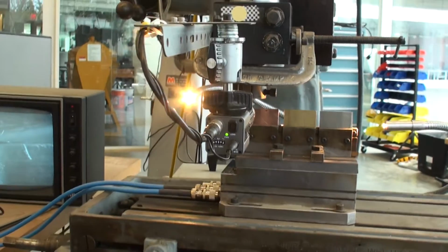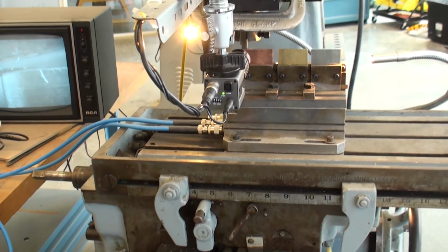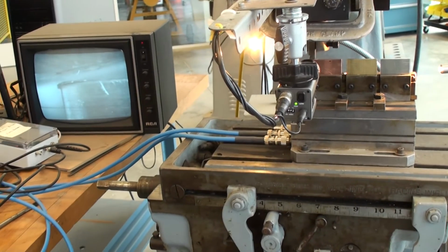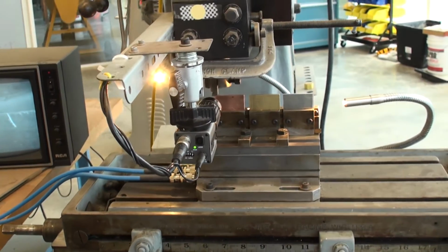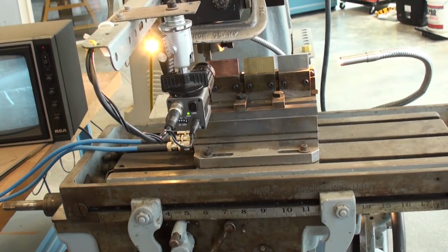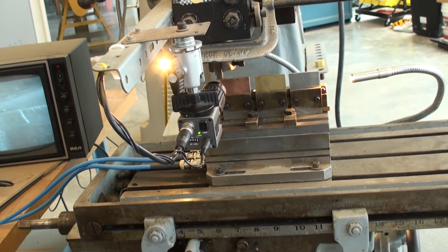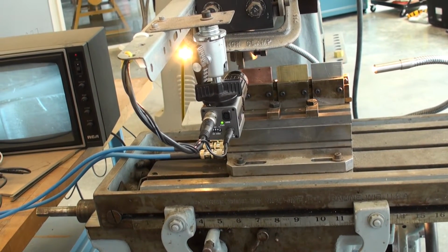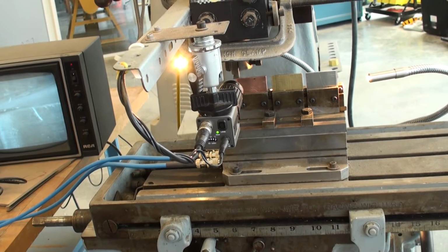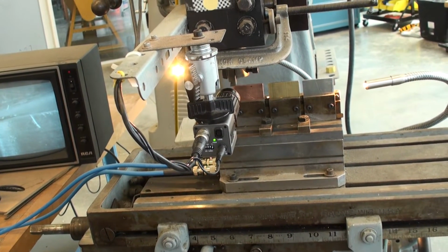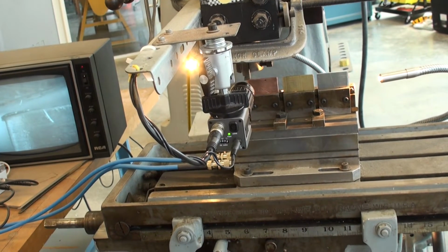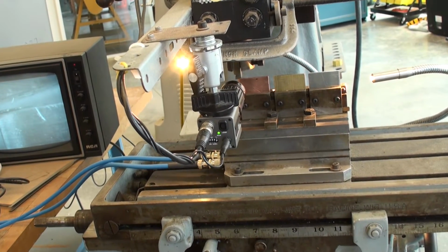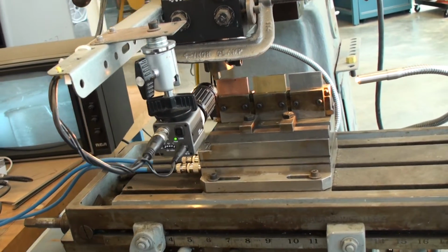Okay, so we've completed the feed rate of 1.5. Here are your values. For aluminum, your chip thickness is 0.02025. For brass, it's 0.03012. Sorry, I'll read that again for brass, 0.03015. And for copper, 0.04000. Now Dominique is going to show us resetting the machine and adjusting our feed rate to our final value of 2.3.